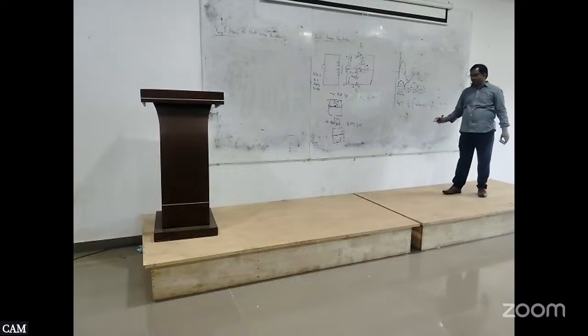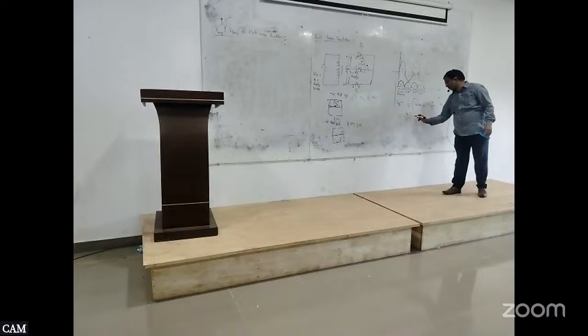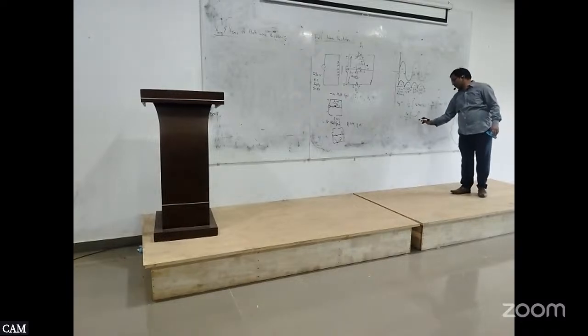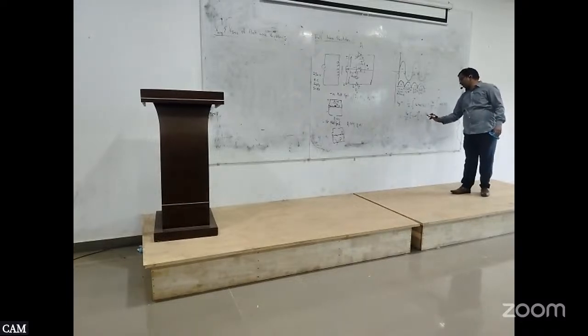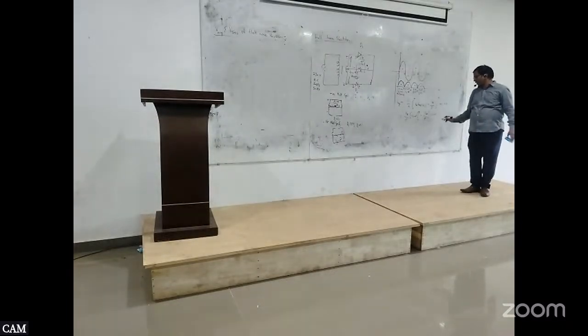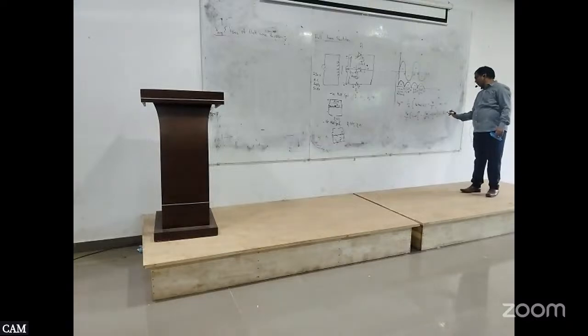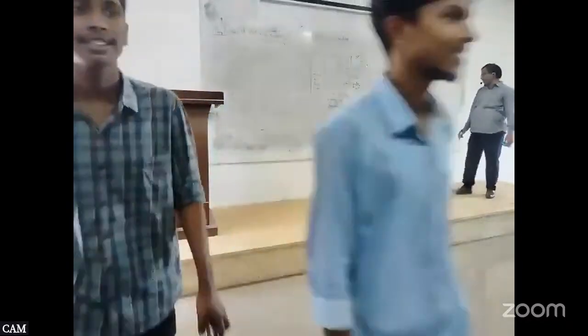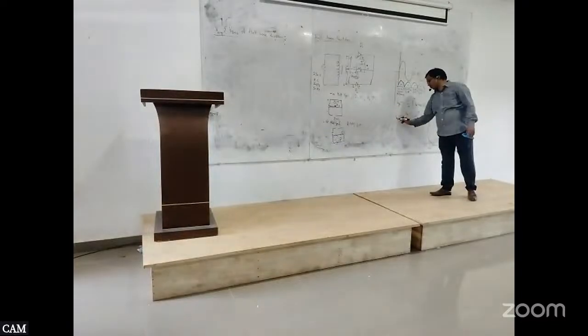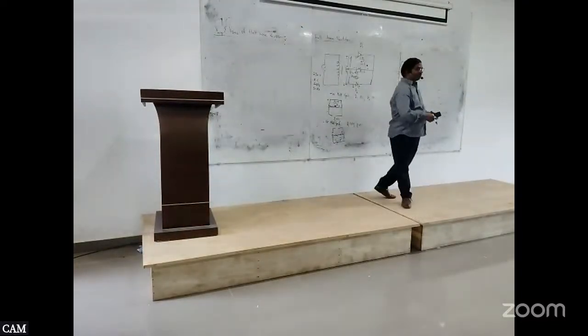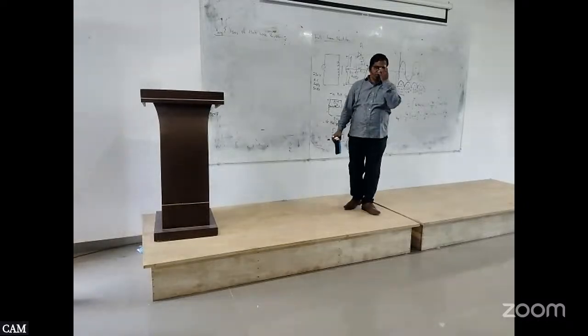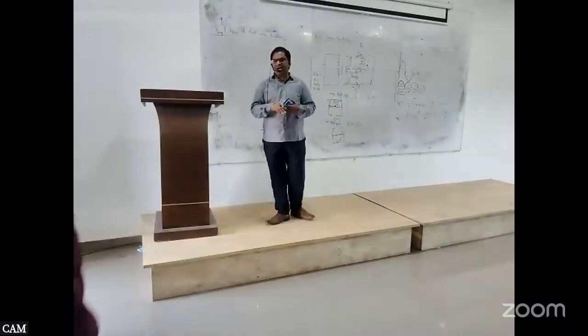The integral of sin theta is minus cos theta. So Vm by pi, minus cos omega t from 0 to pi, which is minus of minus 1 minus of 1, that is 1 plus 1. So it becomes 2 Vm by pi. So the average value of the full wave rectifier is 2 Vm by pi.